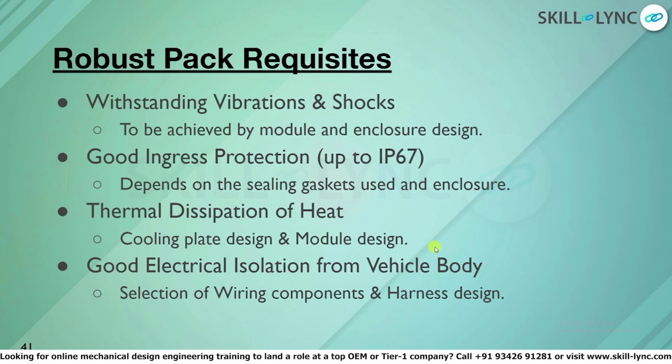And imagine any of the packs in India, with water puddles and non-uniform roads. The pack is going to be subject to a lot of vibration, and with that vibration, if your sealing is not good, the sealing just gets damaged, and then all the water and dust goes into the battery pack, which could first deteriorate the performance of the whole pack, and then could also lead to catastrophic failures like short circuits, etc.